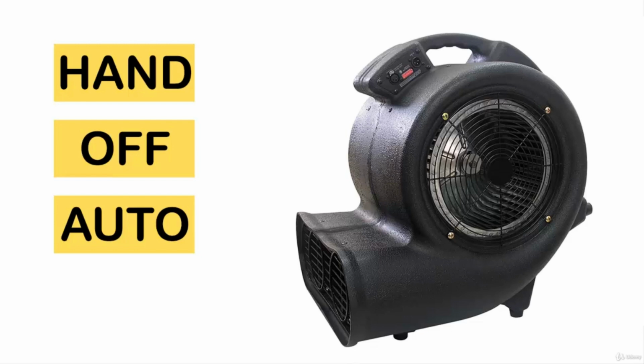Hand is a technical term for manual, which can be implemented in several different ways, and these are considerations that have to be made up front before programming. When we put this blower into automatic mode, that means the process is going to turn the blower on and turn the blower off automatically. When we turn the blower off, the blower is not going to run under any circumstances. Where we have some flexibility is with the hand or manual control, and there are several different possibilities of how to program hand.